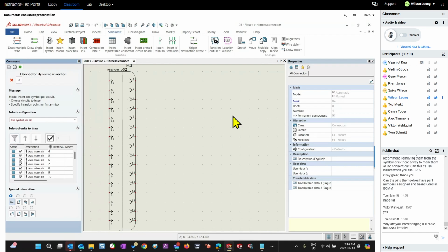I wasted time. So I have 10 pins now, and I'm going to go right click, right click, right click, right click, flip orientation. So if I want this orientation, I'm going to drop it here. So I'm adding 10 pins from here, but maybe I can skip number 8 and 9, pick 11 and 12. Maybe I want to move 12 before 10. Select your number 12, use your arrow keys, and you can move it up. So see, I can start moving it up the way I want. So you can move your pins up and down.